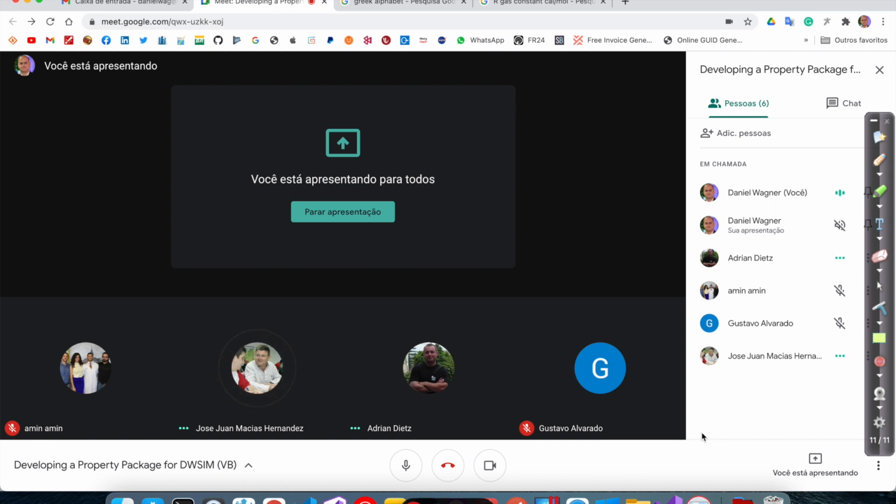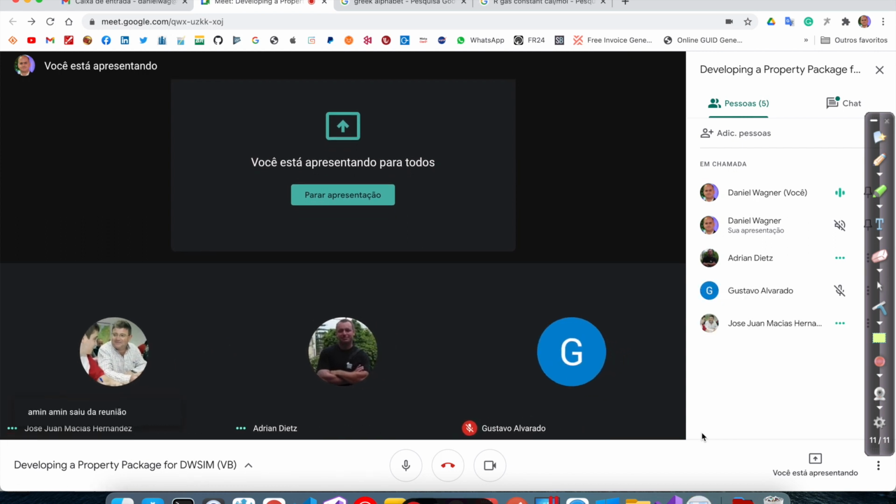Yeah, we have the methods already in DWSIM. For instance, if you want to generate the assay from the stream data, we can calculate everything backwards. Instead of generating the pseudo compounds, we can generate the curve from the compounds from the stream data. I'm not sure if this is what you're asking for. Yes, that is what I'm asking for. You let me know exactly what you need, which methods you want, so I can go straight to it. And okay, I will forward to you an email with that information.